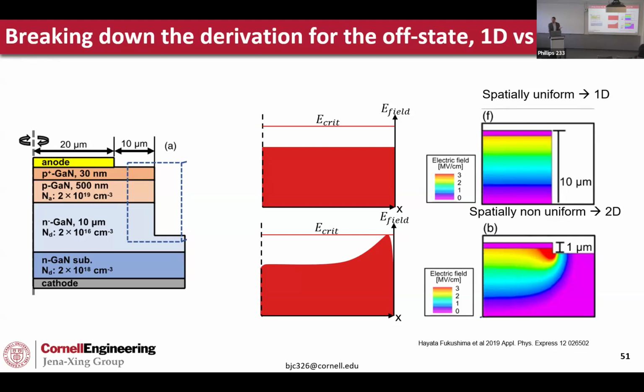That's partly why there's a lot of interest in high K work. But you could also do the same thing with a PN edge termination or insulating edge termination. You just want to move charge away from that edge. You could look up junction termination extension. There's a lot of different terms out there, but mostly it's just moving the concentration of charge away from that edge.